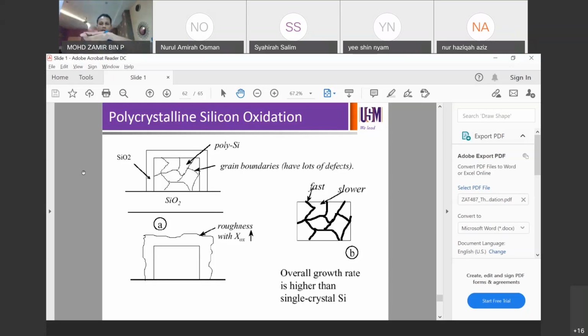But when I used the glass, I used a big piece of glass, about 5 by 5 cm. That's like one third of a short ruler, which is 15 cm. So 5 by 5, and the whole surface of this glass is actually polycrystalline silicon. When I went to the etching process, I removed some of the surface, so I could actually see the grain size. So in that particular case, the grain size can be as big as centimeter by centimeter squared.